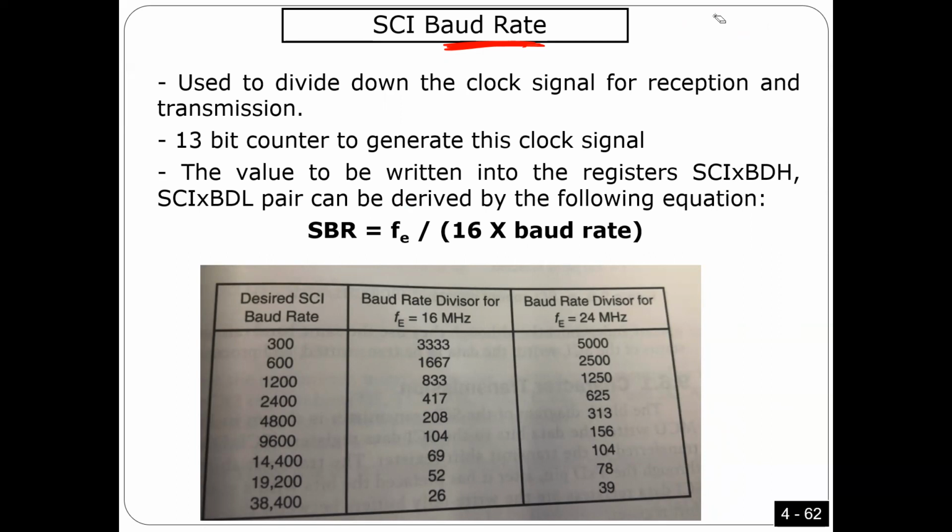As shown here in this table, this is the baud rate I can get. As you see, I can have many different values for the baud rate. So the question, or what I'm going to answer right now, is you can configure the interface to work at a certain baud rate. Again, what's really important here is that the transmitter and receiver both have the same baud rate, okay?